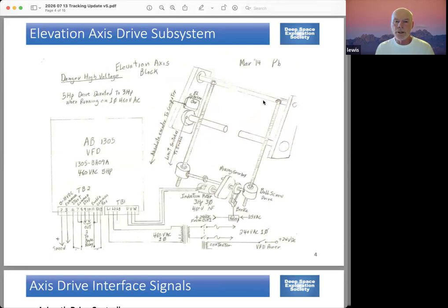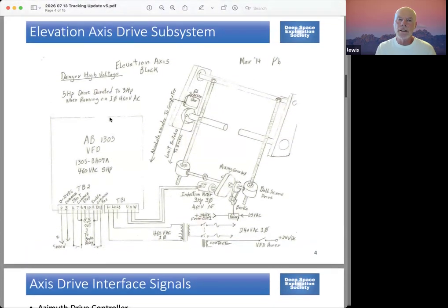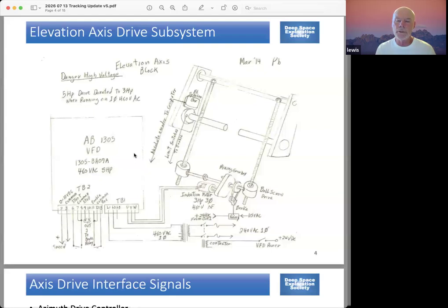And elevation in some ways is similar at a high level. There's a motor controller, it controls the rate of the motor. And I will emphasize that both motor controllers are controlling the rate of the motor, not of the actual axis. But since they're direct coupled mechanically, the axis rate is directly proportional to it. So in the case of the